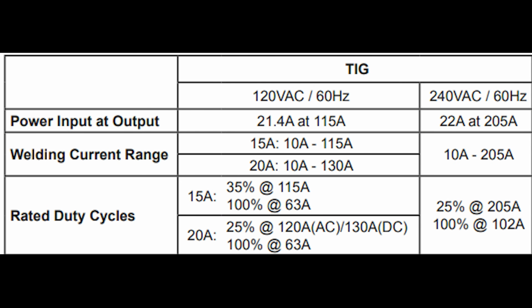Directly correlating with the amperage is what's called duty cycle, and it's something you really got to watch out for. With aluminum, because it takes so much heat input to actually weld it, you tend to run a lot higher on a duty cycle than you normally would. A great example would be, I can weld 1/4 inch or 6.4 mil steel at about 140, 150 amps with any kind of DC TIG welder, no problem. Well, with aluminum, 1/4 inch, you're going to need 200 amps, and you're going to be flat-footed at that, and you're probably not going to have enough heat input.